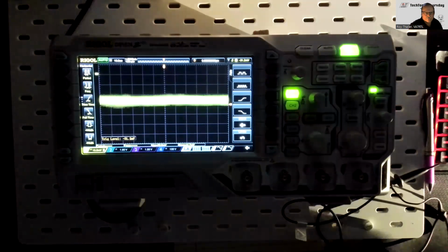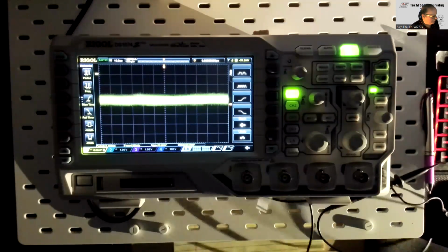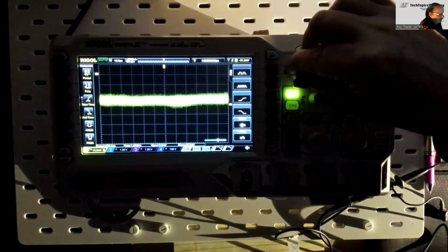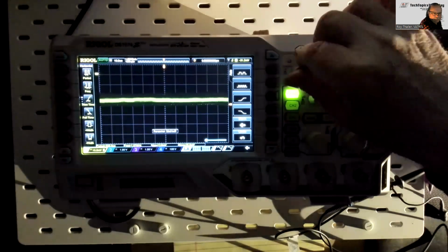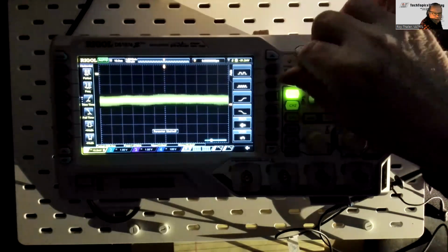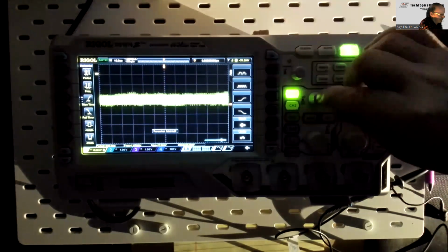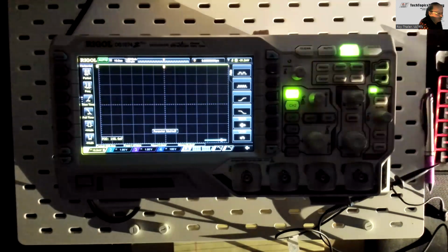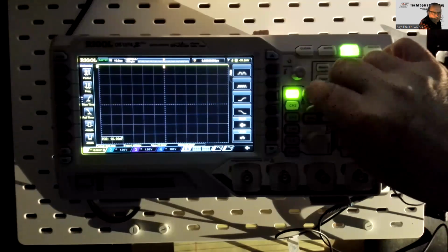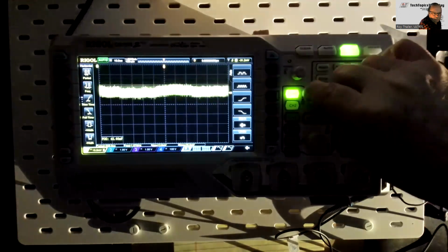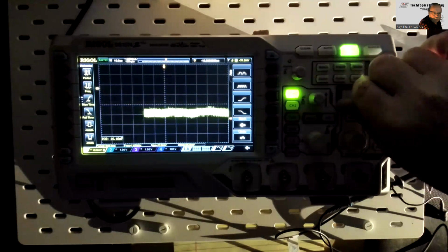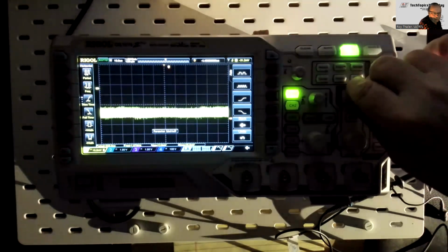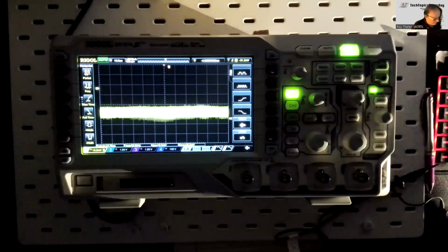What it's doing now, it's set at the most sensitive level because there's nothing set in. So that's what you get. It is possible that the intensity could be turned down so that you might not see anything. Or, for example, this controls the position of the signal, so someone could have adjusted it so it's off the screen, and you have to bring that down. And on your horizontal side, someone could set it so that the horizontal is off the screen too, and you'll have to find where it is. So pressing the auto button is the best thing.